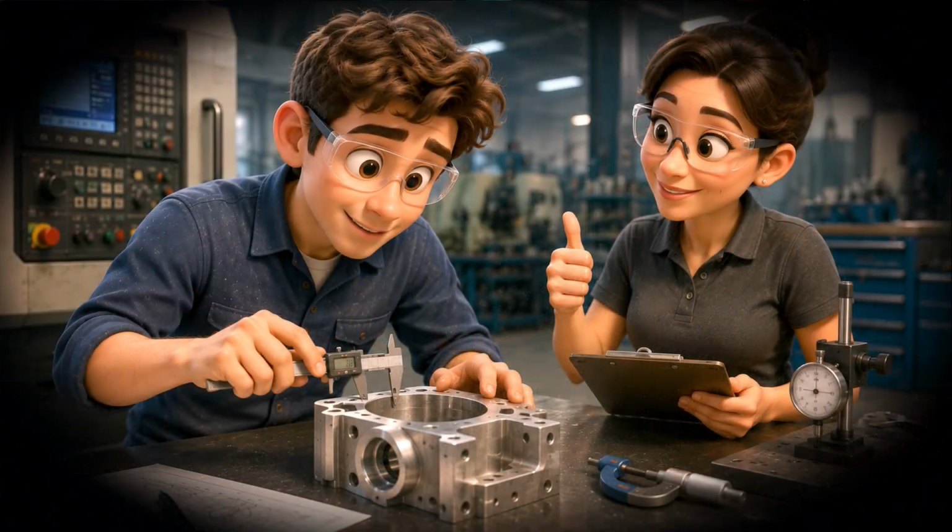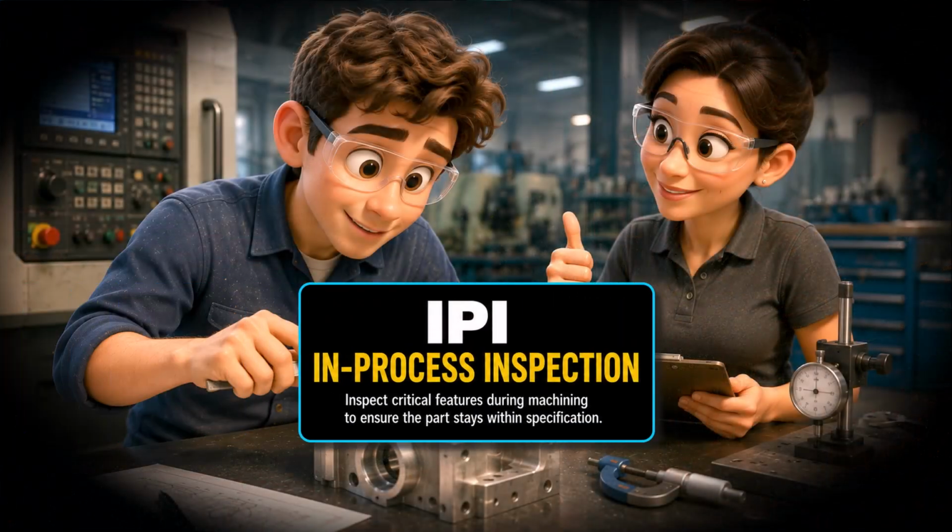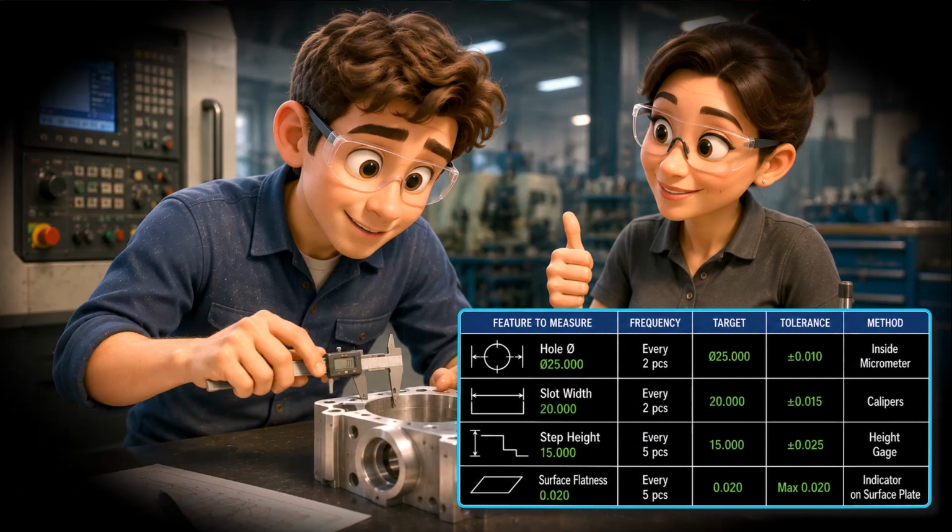Now let's talk about IPI, our in-process inspection sheets. IPI helps verify critical dimensions during production, not just at final inspection. Think of it as catching problems early, before the next operation, before scrap, before the customer sees a problem. IPI tells us what to check, when to check it, and how often. Good in-process control helps prevent escapes.